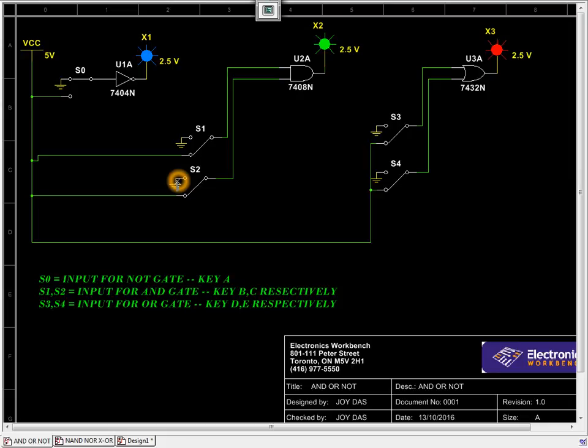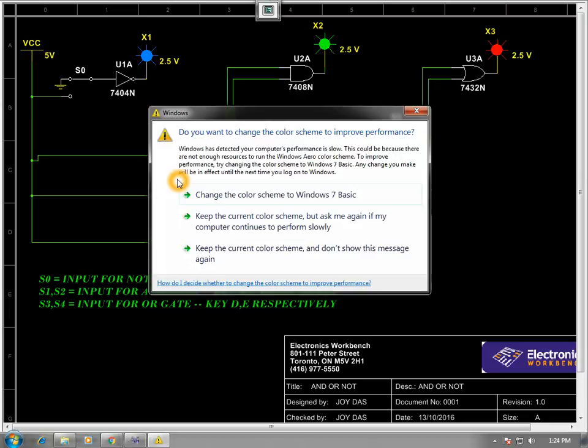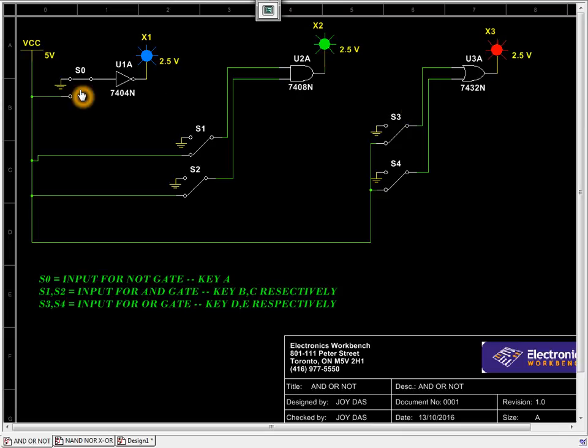The switch that I have used here is a simple SPDT switch, that is, single pole double throw switch. Single pole means a simple 5-volt supply will be thrown to the inputs, and double throw means one way we can connect a source to one load, and the other way we can connect to some other load. Here I have rotated the switches, connected the ground here, and connected the VCC through here.